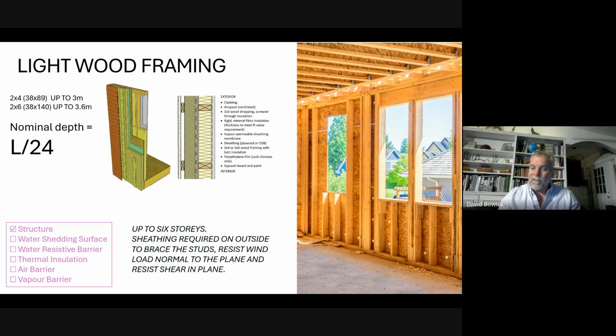So for small buildings, fine. Like if your building is sufficiently small, it's fine, because you've got drywall on the inside, and that's going to carry a certain amount of the burden. It'll carry some lateral loads. It is a panel product, but the capacity is much less. High capacity, we need OSB or plywood on the outside.